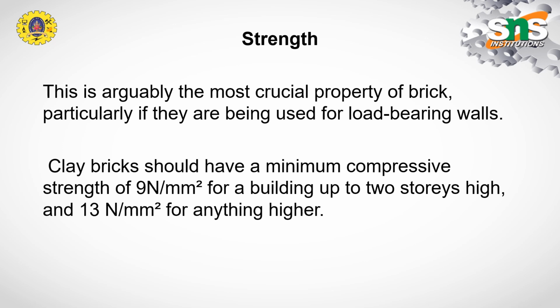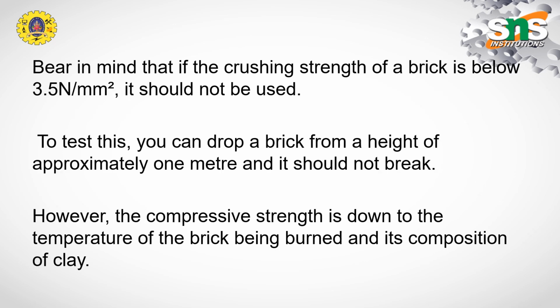The crushing strength of the brick should not be below 3.5 newton per millimeter square. If the crushing or compressive strength of the brick is below 3.5 newton per millimeter square, then it shall not be used. So how do we find whether it is a good brick or not? There is a simple procedure.